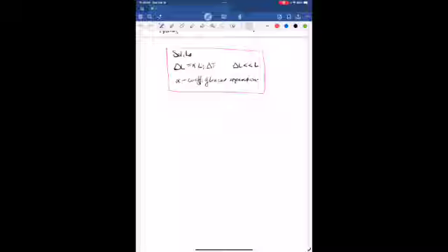And alpha, the coefficient of linear expansion, is measured for various different types of solids, and they are tabulated, so you can find them in tables in your book. The table that's in your book is one of the tables I'm giving you, but you can also find these on the internet. Now, this does not work for liquids because liquids do not preserve their shape when they expand or contract.